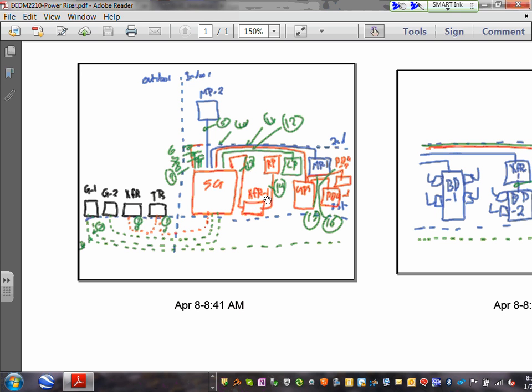You need one transformer to feed the receptacle panel, and then we'll need the lighting panel. Then we need a UPS with PDUs right next to it. The UPS with PDUs will be set in a different location. We need mechanical panel 1 and mechanical panel 2 in the upper floor. Okay, can you guys see that? These two panels, mechanical 1 and mechanical 2.